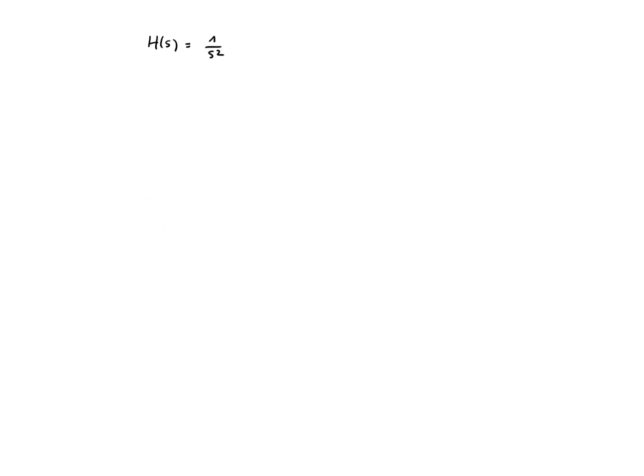So let's do a little exercise on writing state space descriptions and obtaining the discrete time version of those state space descriptions. So we'll take a double integrator, and in order to obtain the state space description, we can write the system as follows. We say that x2 is 1 over s u.